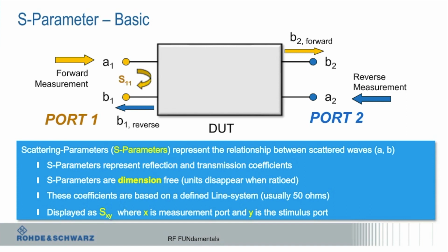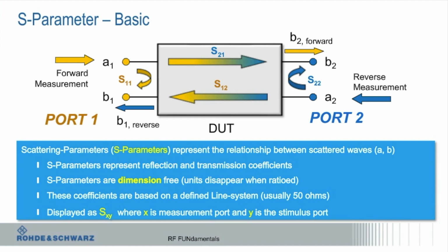Okay, so that's S11. I send out a signal, and it comes back. And I mentioned these before, S22, S21, S12. Those are the basic ones. Realize this is 2 ports, and this generates a 2x2 S parameter matrix. But obviously, I can have a 4-port. Guys who do differential measurements would have 2 in, 2 out instead of 1 in, 1 out. That gives you a 4x4 matrix. And we make one that's 24 ports, so that's even bigger. We'll just leave it at that.